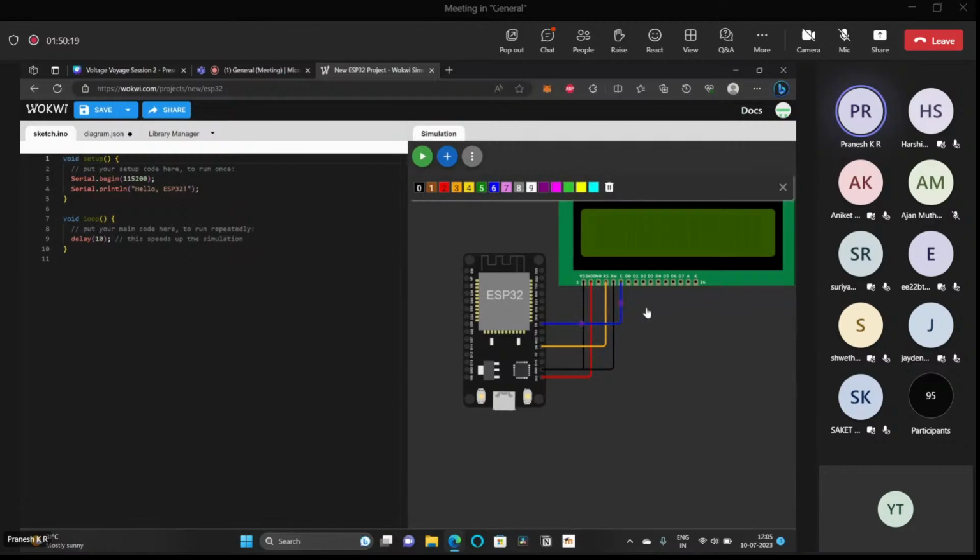Let us again change the color of this. So now we have eight data inputs. Now let me explain the two types of data connections that an LCD display has. It has a 4-bit data connection and an 8-bit data connection. We generally use 4-bit, and for now we'll use 4-bit, and I will explain how to use 8-bit data input as well. You see, 8 data pins. We'll just use 4 data pins to display stuff on the LCD display. And at the end of the session, if time permits, I'll explain how to use the 8-pin data input as well.